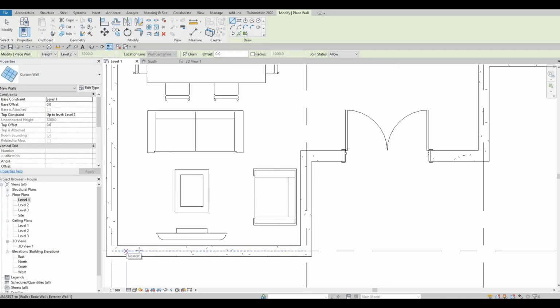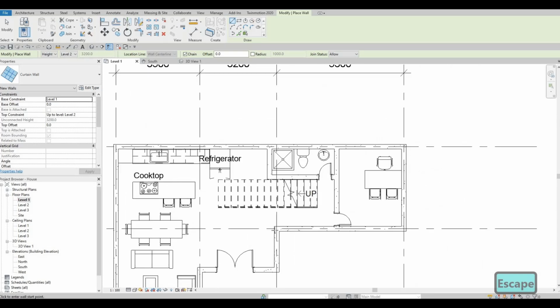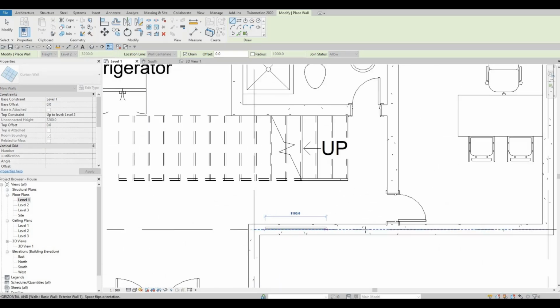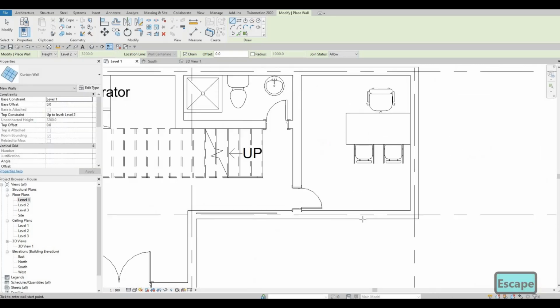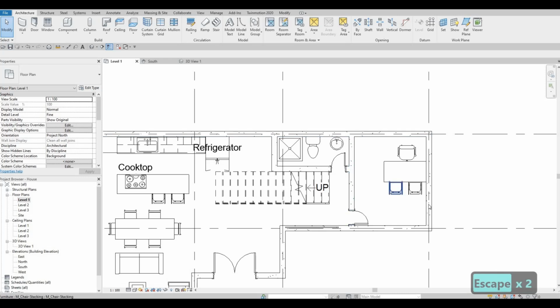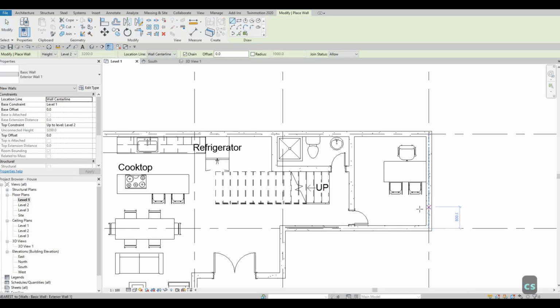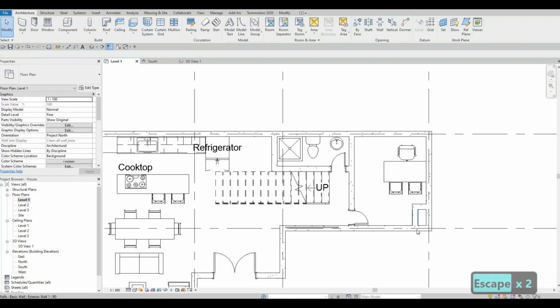Here I'm gonna include a curtain wall right here. And then we could add in a curtain wall right here so that it will give sunlight. I'm gonna change this corner. So what I'm gonna do is I'm gonna select this wall, so exterior, type in CS or create similar, and I'm just gonna create a nook like so, and then TR, trim and extend.